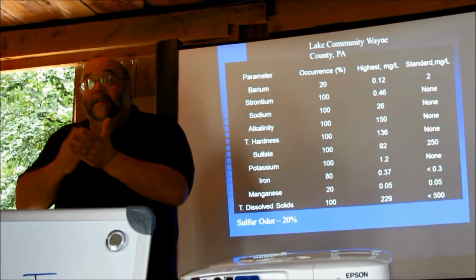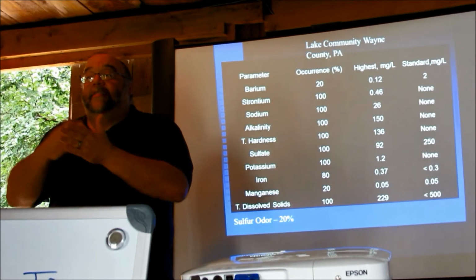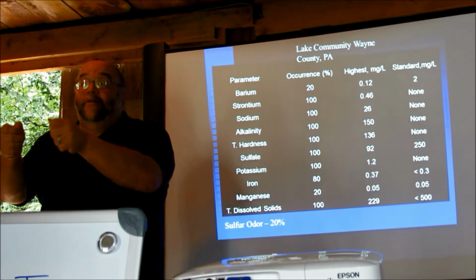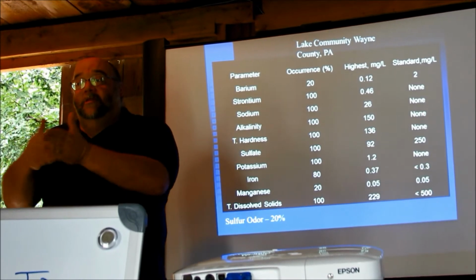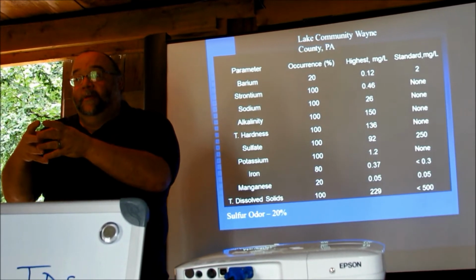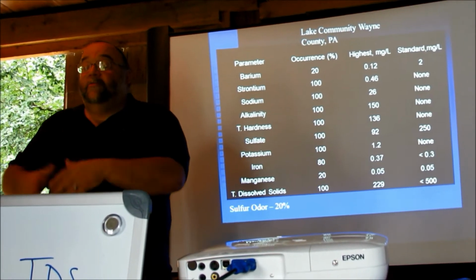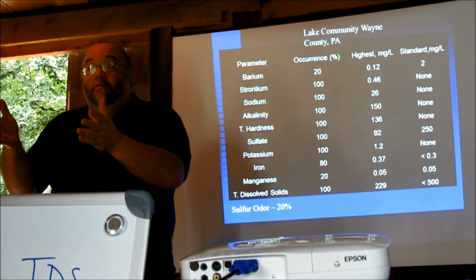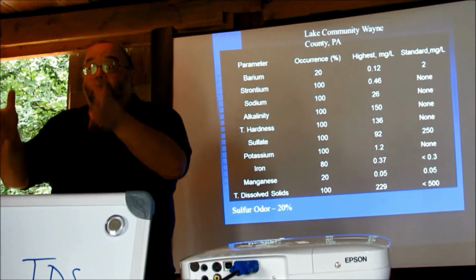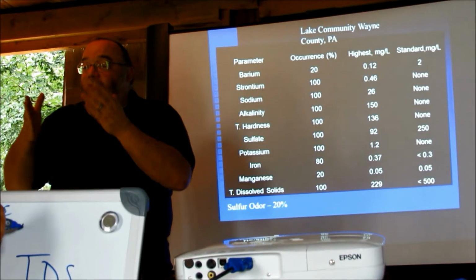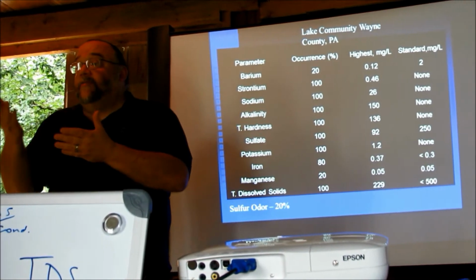If you already have TDS meters, get people to do TDS, check what the ratio should be, and program the value right in, and tell them to only use this meter for this application. Because you don't want people to generate bad data, raise a red flag, and be wrong. We don't want to cry wolf, because then we start looking bad. When there's an issue, we want to document it, and that's why photographs are important.